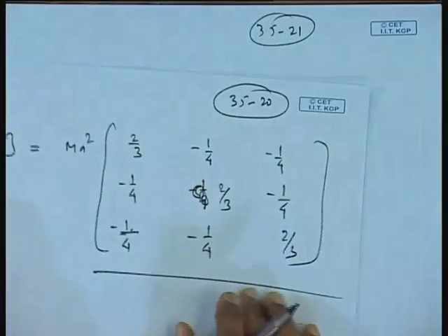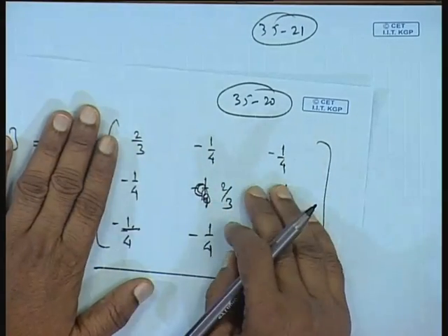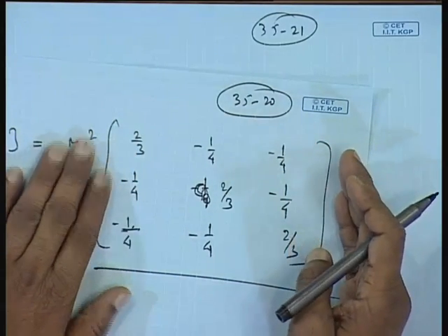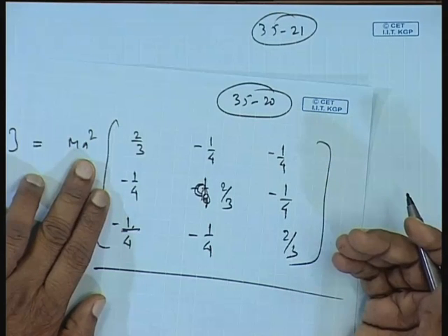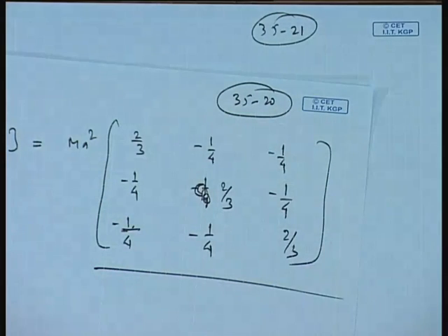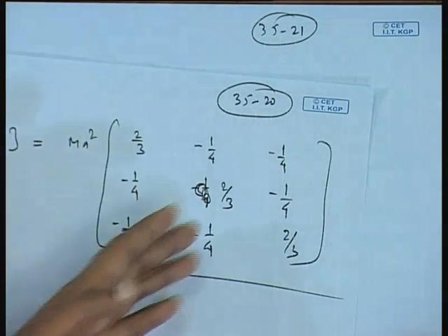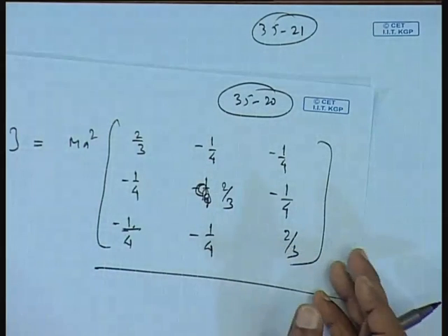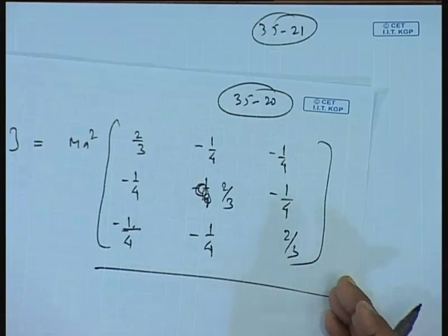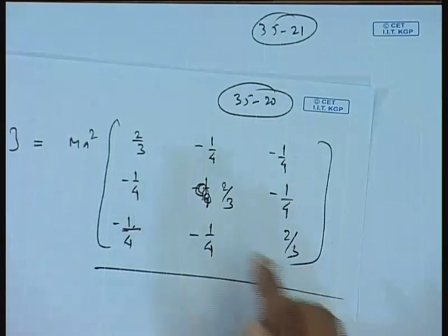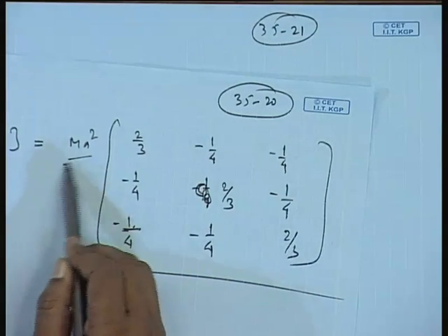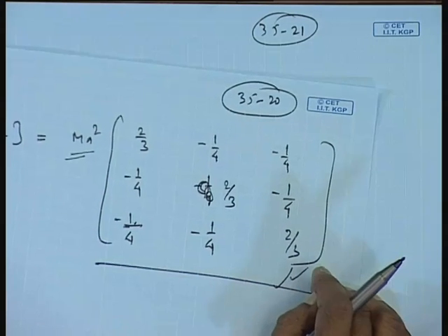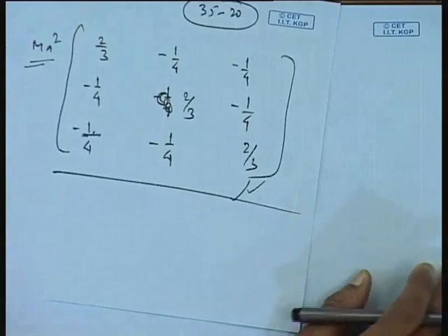So, for solving for the eigenvalues, what can we do? We can work only with this matrix here, which has the numerical values, and whatever eigenvalues result, we multiply by m a square. So, the result will be the required result. Or either we can keep it inside itself, then subtract the corresponding lambda in the diagonal terms and solve for the determinant. Okay. And there you get the eigenvalues, which are the lambda, where the m a square term will be directly appearing. So, both ways you can do, but working with this is obviously much simpler than the other way.